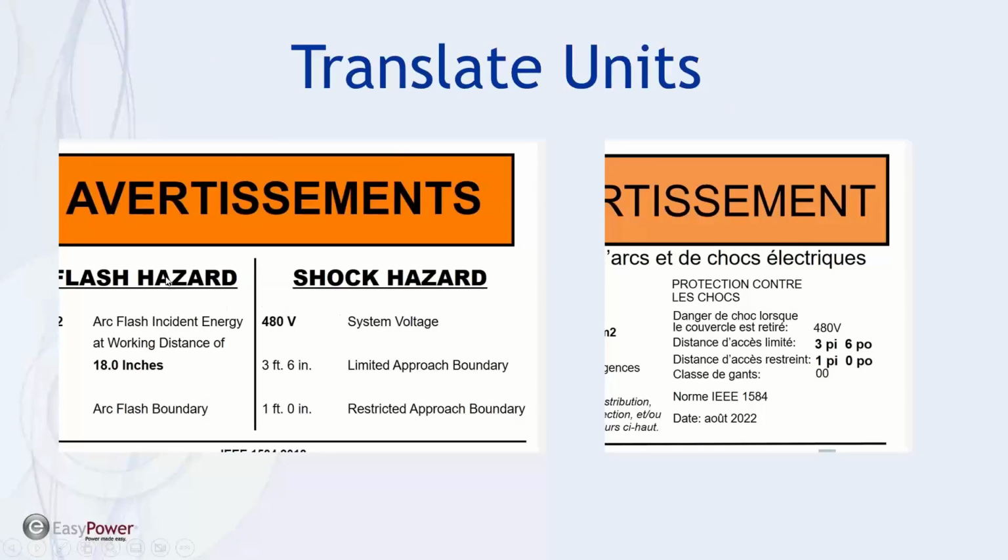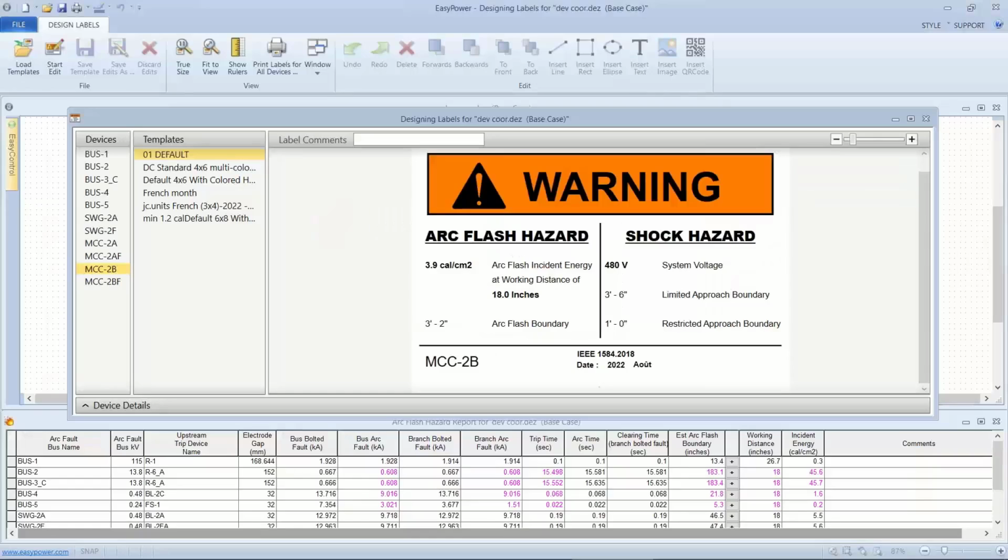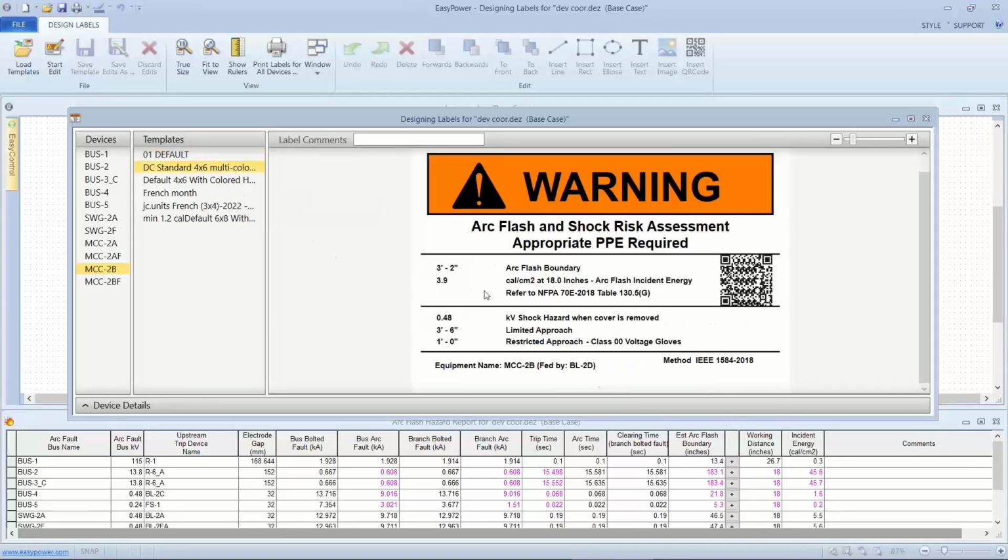Chuck's saying, since the label does not show PPE level, what would you typically indicate the reference as where to customer to go to log? Okay, so the question, I guess as I understand it, is the reference point for the label for the PPE, and that can be accommodated with additional verbiage that says, let's see what we're showing here, refer to NFPA 70E 2018 table.